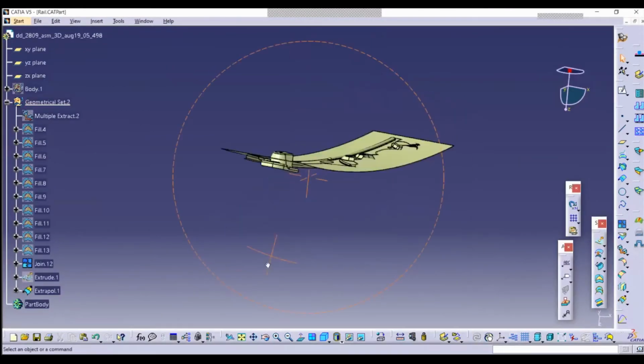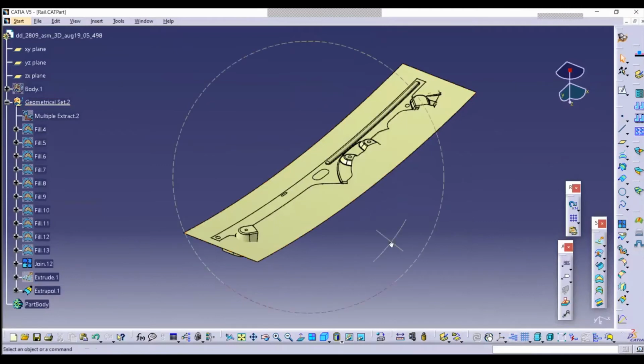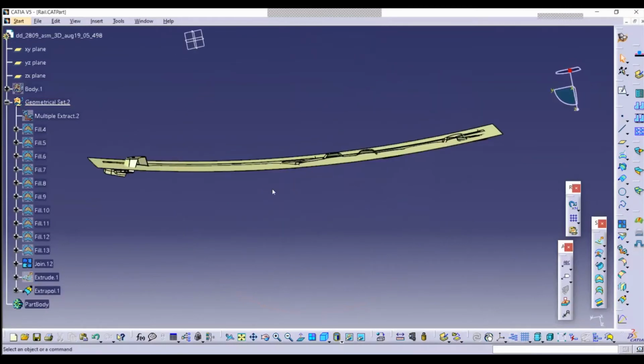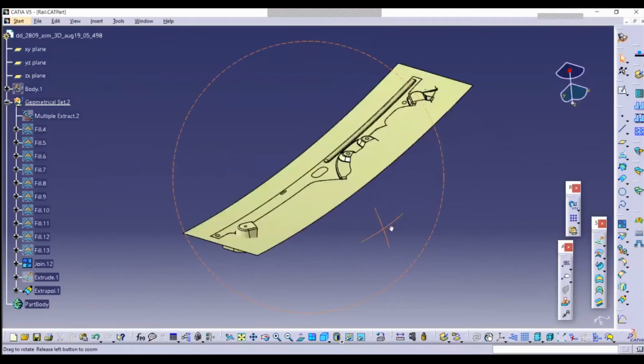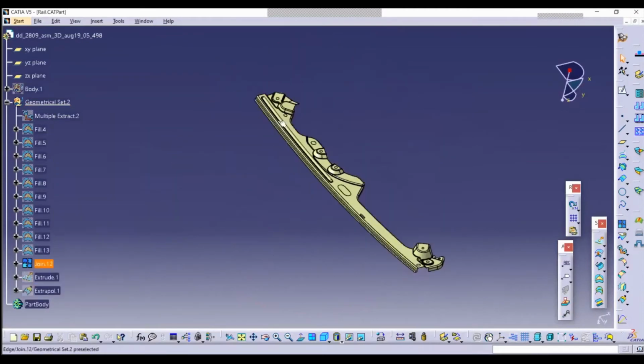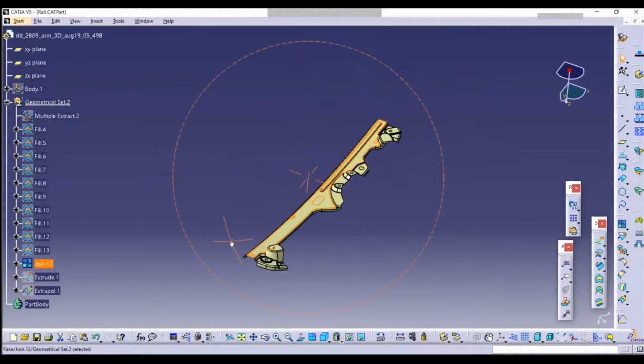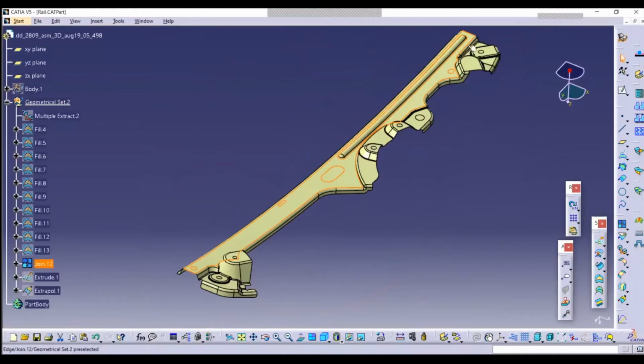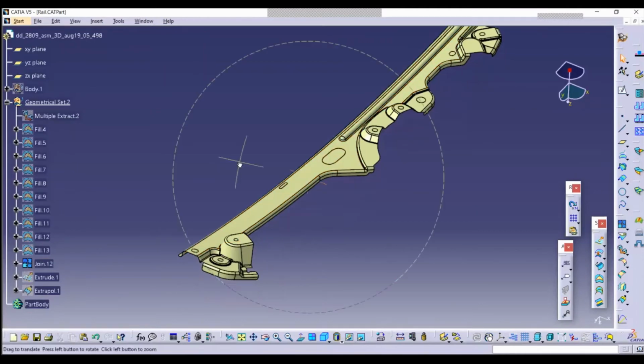So what I've created here basically is an unfolding surface. So a surface that I'm going to use to pre-curve the blank. The other reason that I do this as well is when I do the simulation, I'm going to want to hold the part along this surface here with what we call a pressure pad or a holding force to keep the part from moving as we do the unfold. Because the part is curved, I need to use a curved binder to make sure that it does the intermediate unfold to give me the proper length for the part.